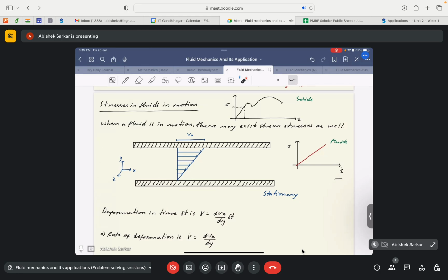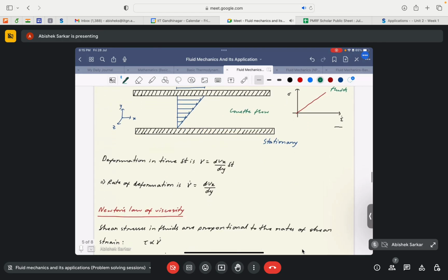So is that clear, what we mean by the driving factor of a flow? It's fine if it's not clear, because it will only become clear when we discuss different examples with different driving forces. In the case of pipe flow, it is the pressure gradient that drives the flow. In the case of a boundary layer, it is the inertia force of the incoming flow that drives the flow. So there are different mechanisms that can drive a fluid flow, but in Couette flow, it is the motion of the moving upper plate that generates the flow.